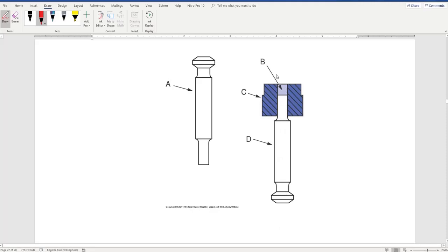See, when I want to fill a material, this material comes from a hopper shoe. Here I will have a hopper shoe, coming from a hopper. It will fill the material in this place. Now if I lower the lower punch more, I can fill more quantity. Right? If I take it up, the quantity that is filled will be less.